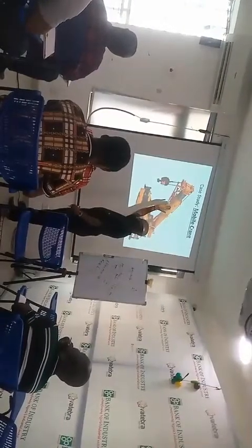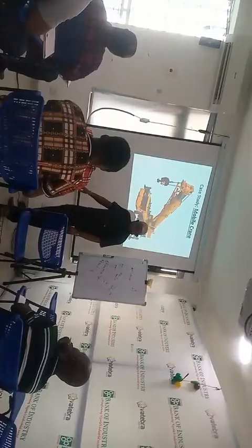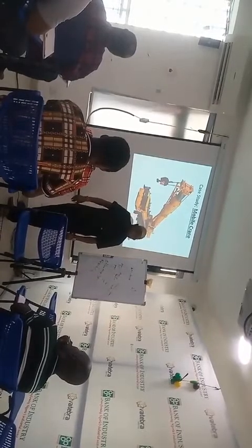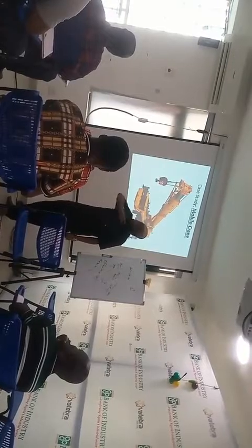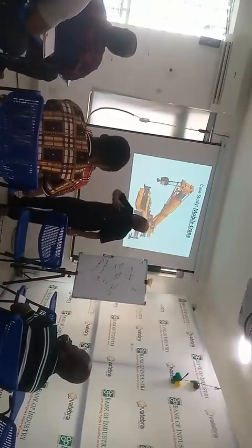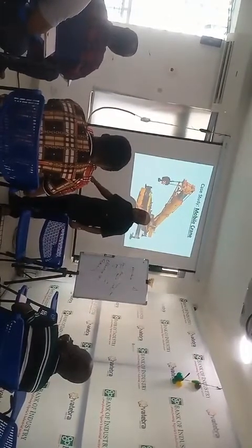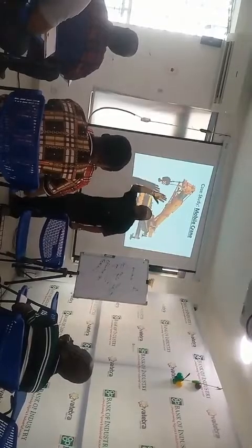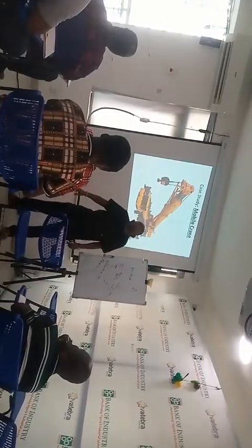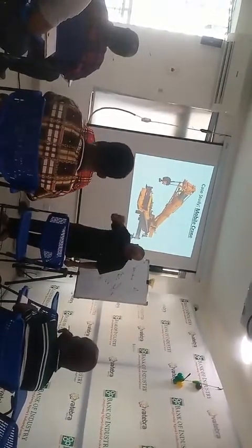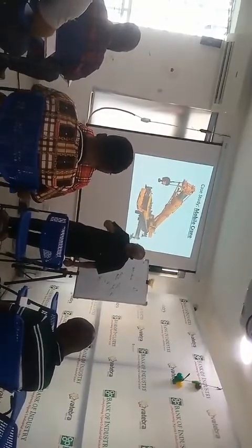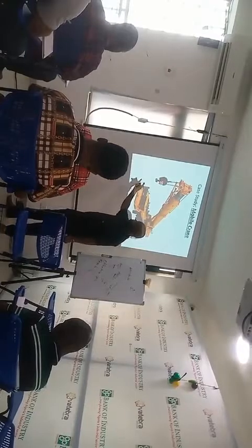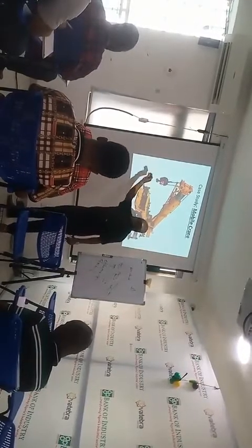And the wires parting, I think you've heard about wires parting. We don't say cutting, we say wire parting. It takes itself off from that load. It parts. Take the headroom, that is the space between the cargo you are carrying and the hook, into consideration.